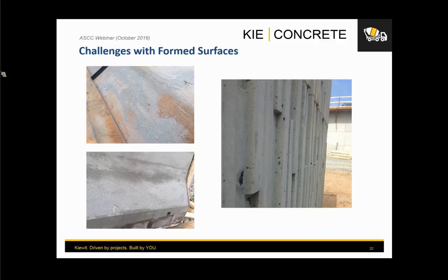In some cases, you have seen that we as contractors do not do our job preparing the surfaces that are going to receive concrete, right? And then when you remove the formwork, you get issues with your surfaces. So we need to make sure that we first understand the requirements, and then that our field operations also understand what they need to do to achieve the finished surfaces that they're required to meet.